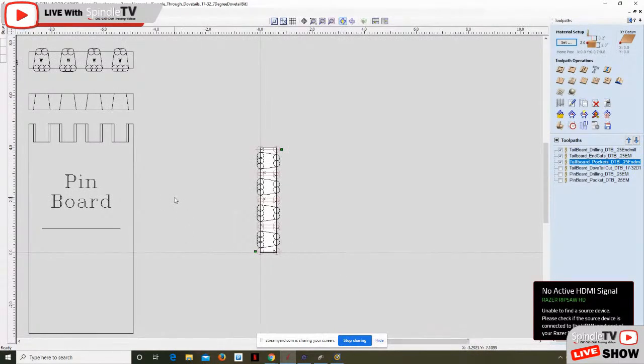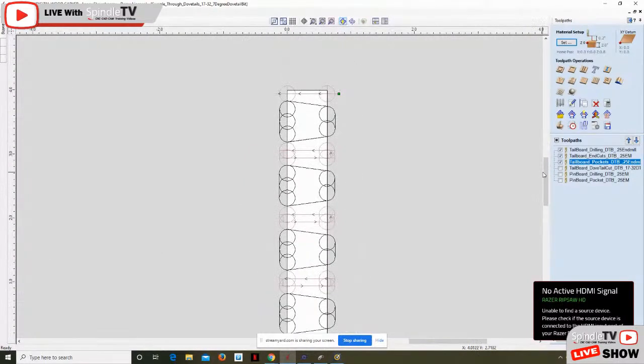In the Vectric software, the width of your screen left to right represents the x-axis, and the height of your screen represents the y-axis. Well, along my x-axis at the front of my table, my joint maker jig is mounted. So my material, which is 5/8 inch thick by 4 inches wide, is going to be up against that joint maker jig. So it's orientated in this vertical layout.